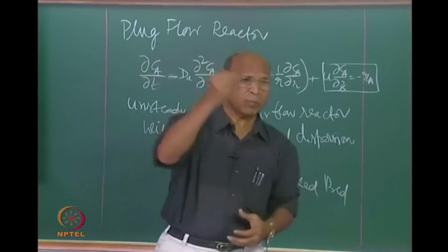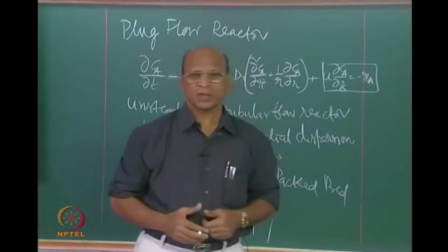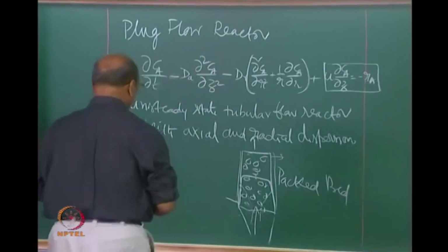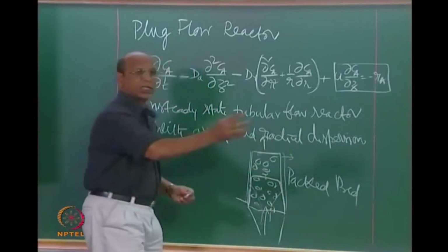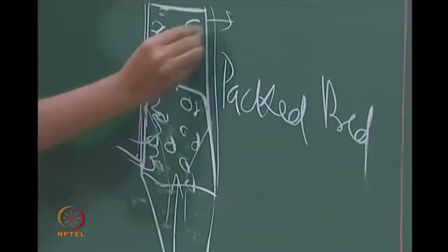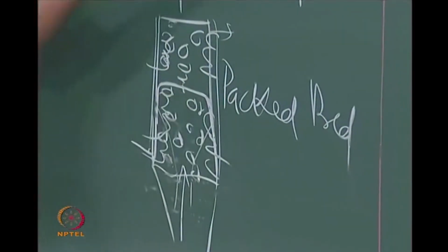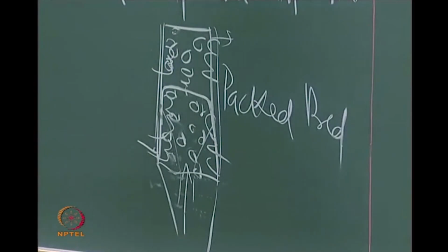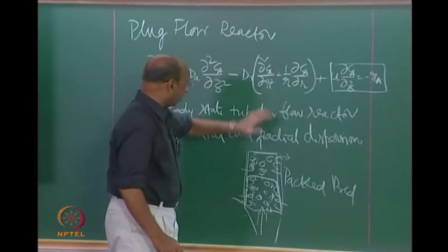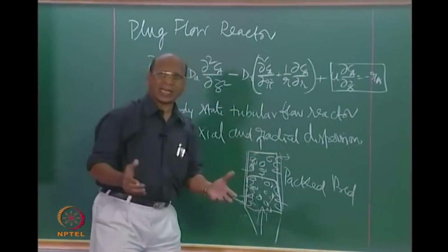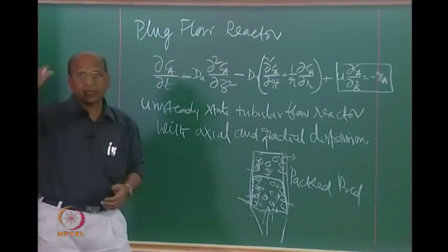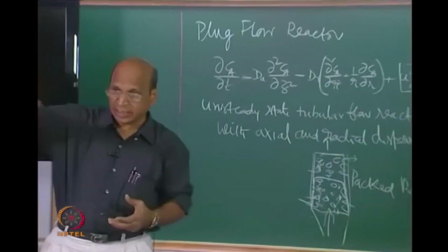So, that is why heat removal also is the biggest problem in packed beds. You cannot put only an outside jacket, sometimes you have to put also inside heat removal systems, inside here like this. So, all this will disturb the flow, right. So, that is why the real expression what you have to use, and when you are also studying the first time, then unsteady state also will come into picture. You have to solve this equation, and then you have to find out when the steady state comes.